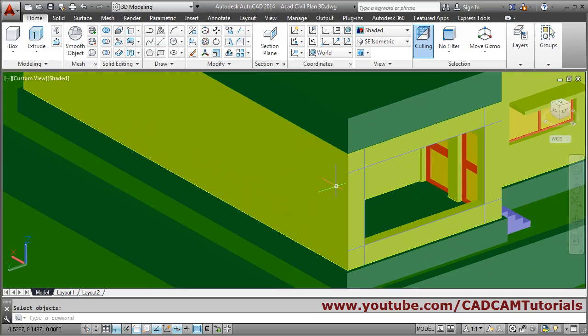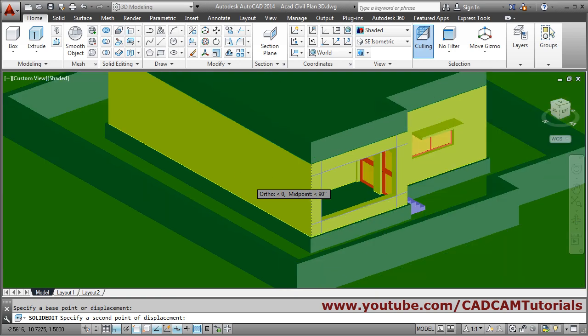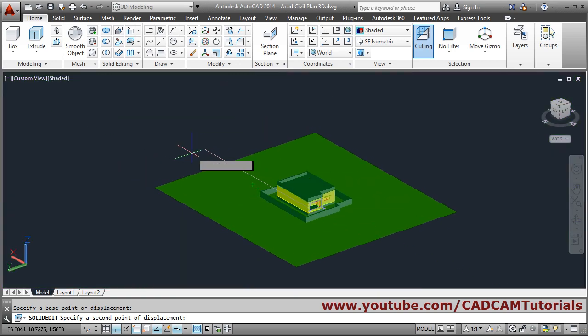So same procedure we will do here. So again copy edge, copy this line, enter, base point direction is inside. Normally it should be taken at empty space, so that it will not take any other object snap and it will not go anywhere at other positions.